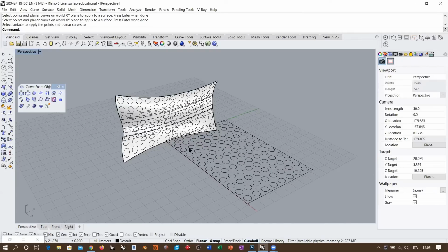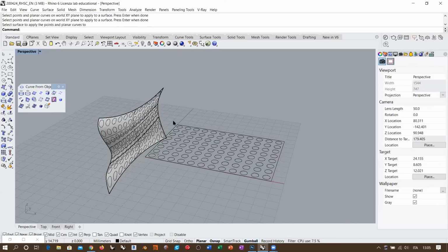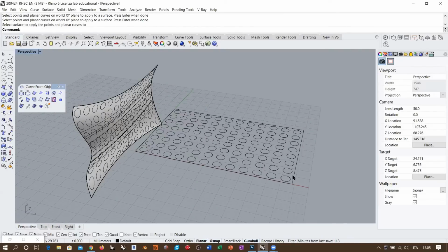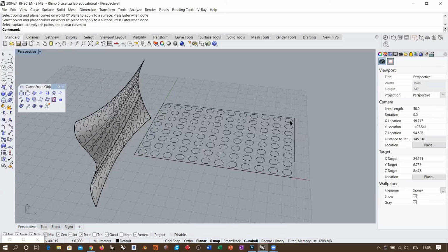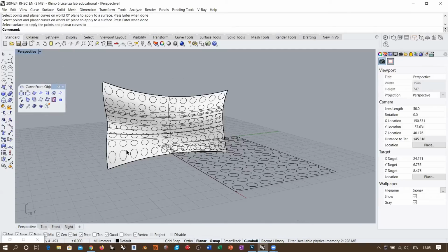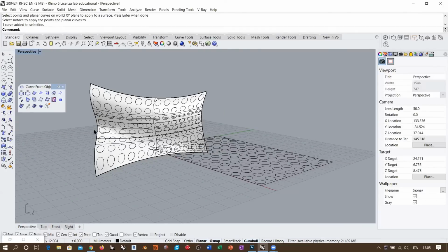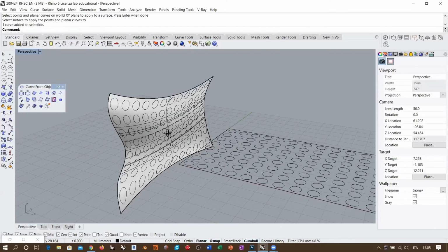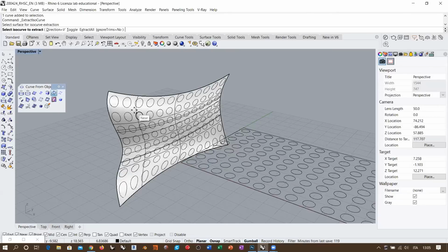So you see that UV curves always produce some deformation, because unless you have a regular topology for the original surface, there will always be deformation between a constant speed of the rectangle, which is a bilinear geometry, and a non-constant speed of this kind of weird topology that we have here, which depends on the topology of the cross-section. Remember that this depends on the topology of the first cross-section, which had those knots added in the center part.